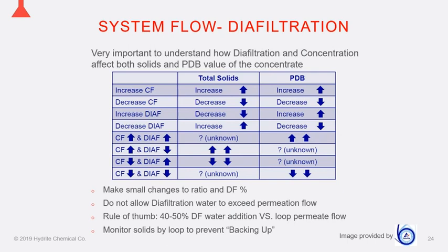Again, increase in concentration factor and diafiltration. What does that do to the total solids? Kind of an unknown. We don't want to over concentrate. It will increase the protein on a dry basis. We have seen some accounts that have over concentrated and plugged their membranes up with protein, and we do have a special recovery wash for that, which will get discussed next week in the cleaning section.